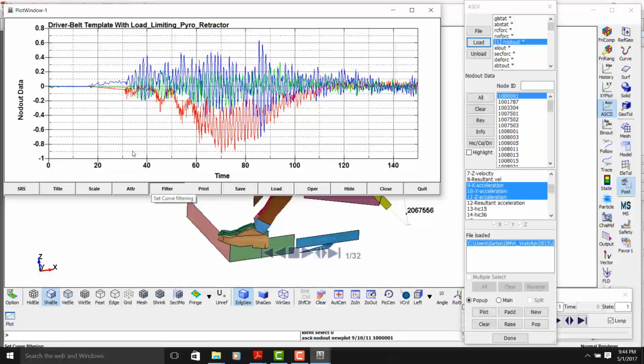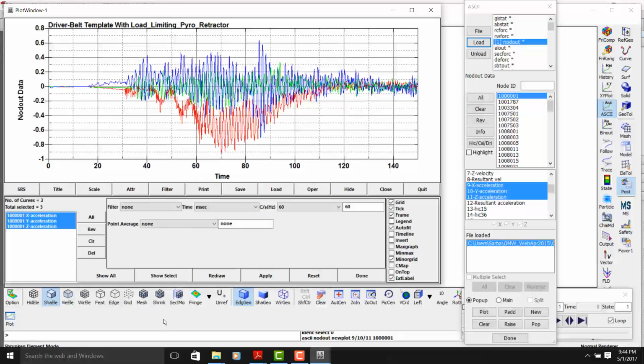Now press the filter button, and here it comes up. First notice the time unit, and it comes up default as milliseconds, which is our time. Okay, if you pull this menu, you can go to second, and you can go to USEC, which I'm not sure what that is. But mostly we need either second or millisecond, and it comes as millisecond, so we don't do anything.